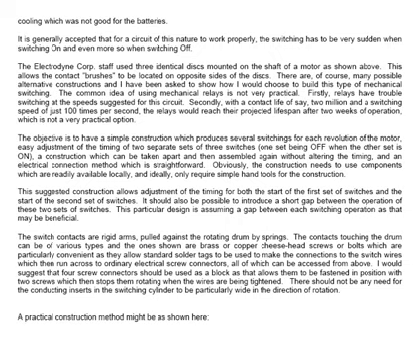The common idea of using mechanical relays is not very practical. Firstly, relays have trouble switching at the speed suggested for this circuit. Secondly, with a contact life of say 2 million, as is normally claimed, and switching speeds of just 100 times per second, the relays would reach their projected lifespan after 2 weeks of operation, which is not a very practical option.